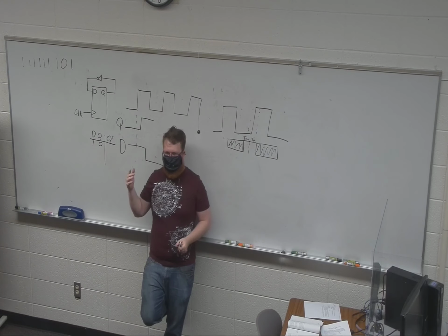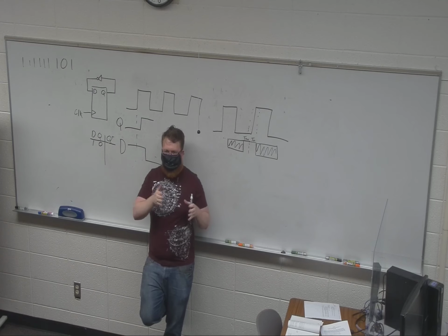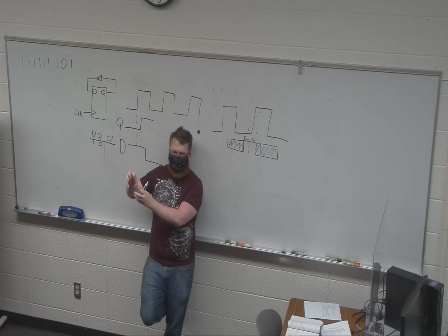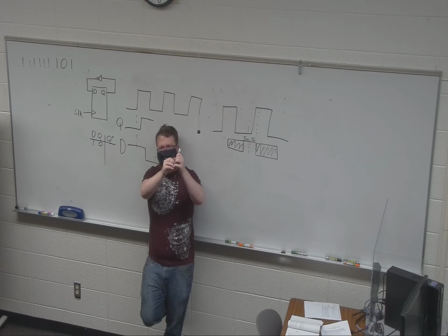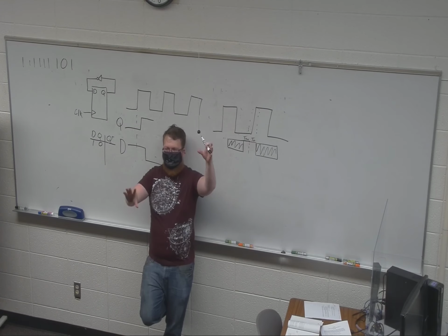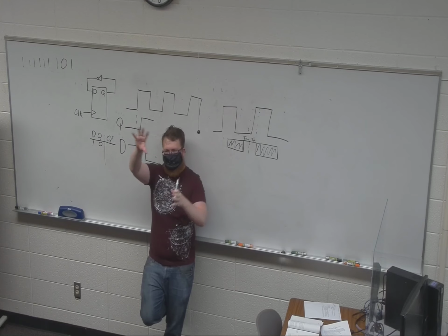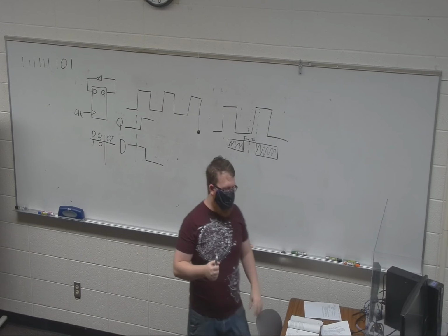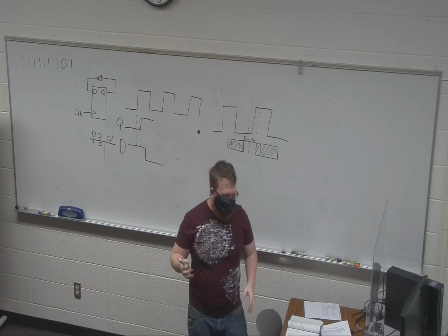Trying to puzzle through, that's kind of what it's talking about, where you have these different system paths that are branching out and coming back together to talk to each other. One of them will have like 12 inverters on it, and the other one has 2, and the delay through them is very different. So let's look at an example where they can happen even in an unclocked system.